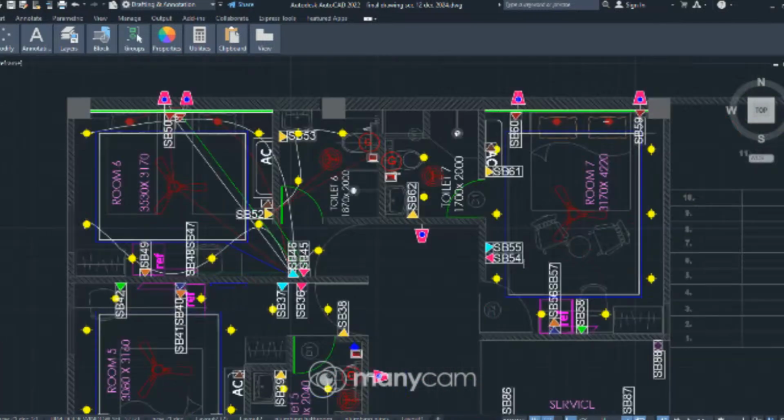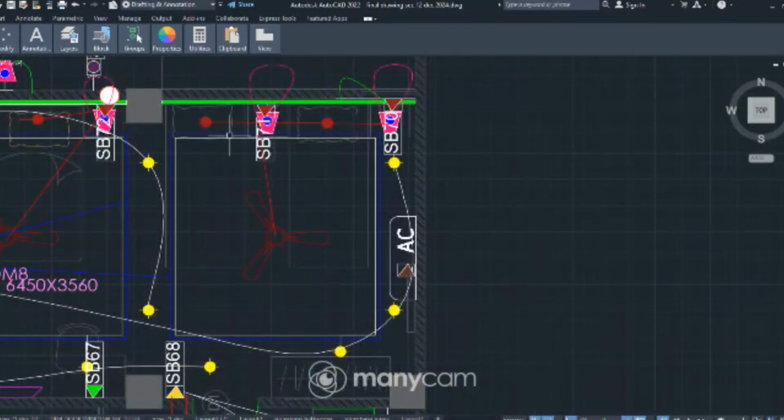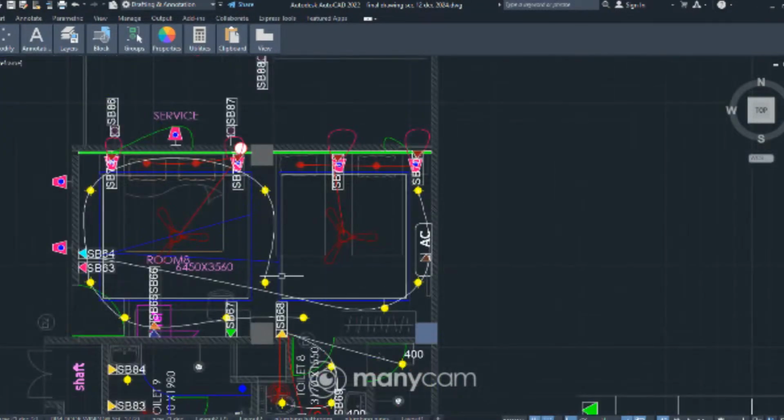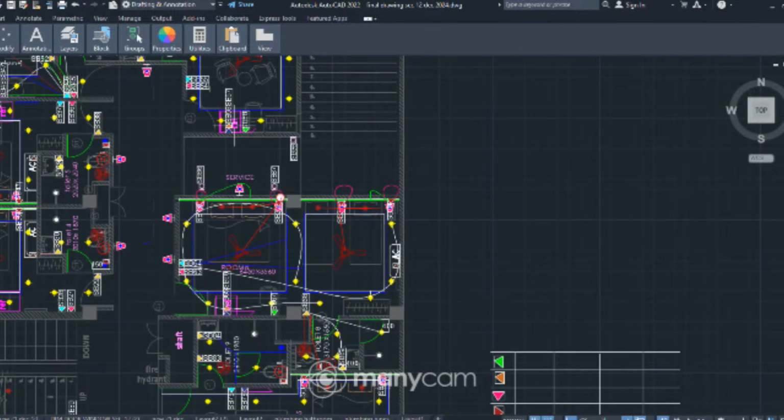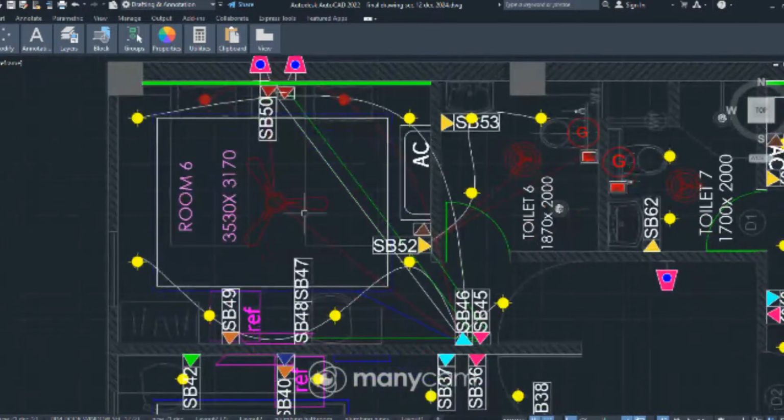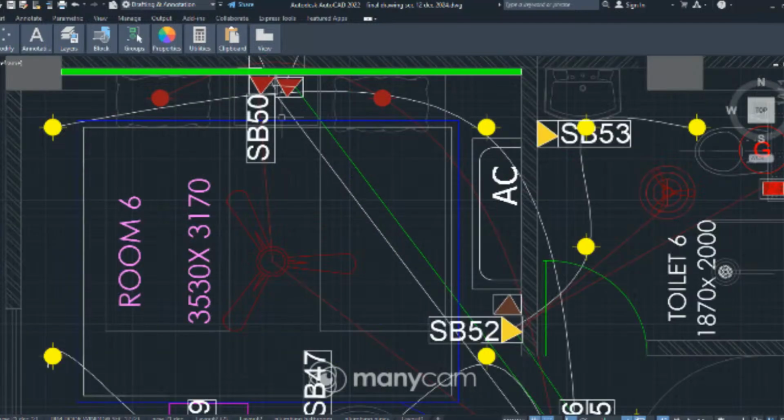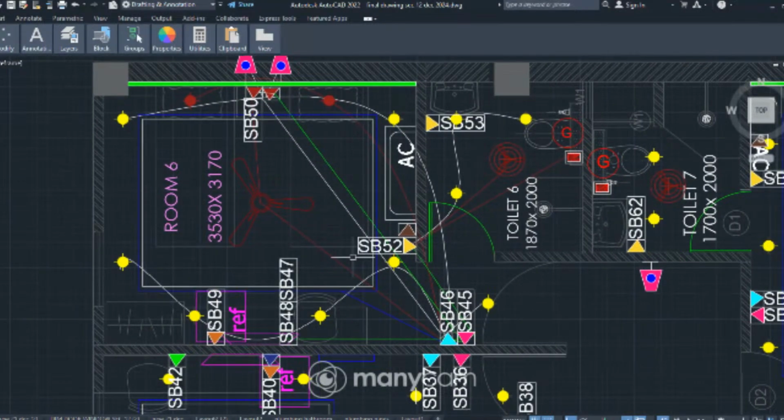Now here I want to show you what I was talking about. There are two ways to place your furniture for twin beds. Either you just give one side table in between and the one on the other side if you have a smaller space, because you need to maintain that walking distance. The passage needs to be given. Or you place a big side table in between the two beds and then you have your walking space. So there we could accommodate two side tables and here we have only one side table.